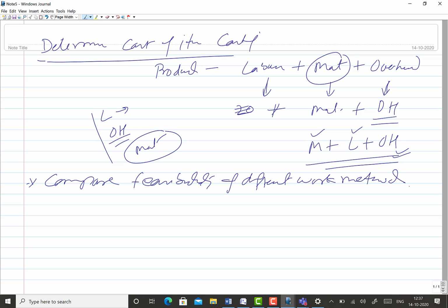Okay, so for doing a job during the method study, what you have identified is that this job can be done using three other options. So there are three alternatives using which the job can be done, and for these three alternatives you can apply work measurement and see how much time it takes through any option. Say it is 12, 10 or 8.